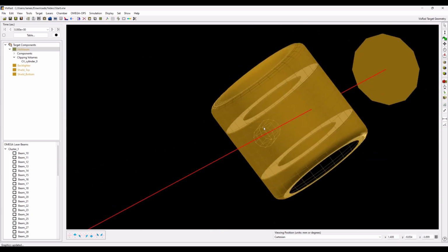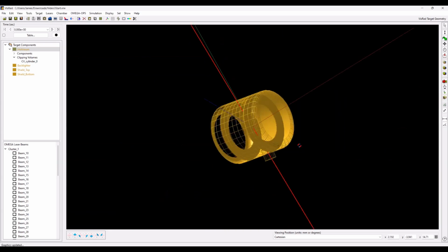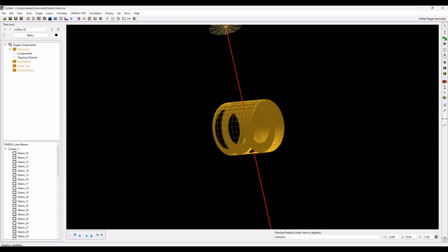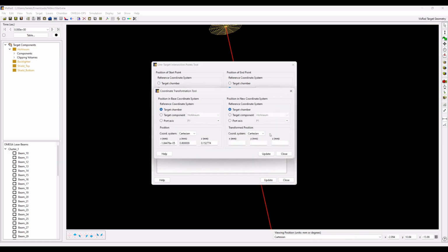And now we can go ahead and add our clipping volume for our material sample. To do that, I'll bring up our intersection list once again, and we'll now use the second intersection point. We'll transform this to the reference system of the hole realm in cylindrical units, hit update, and copy this for the centroid position of our new clipping volume.